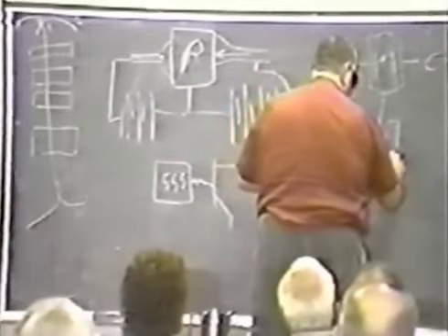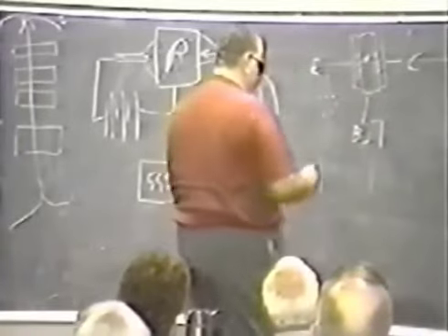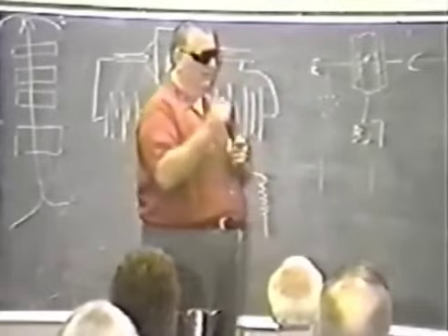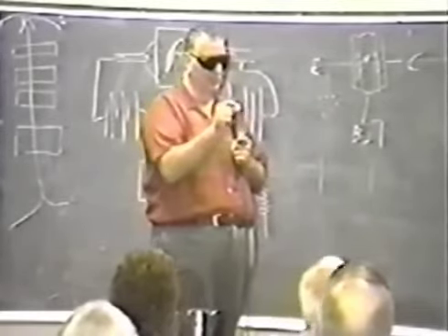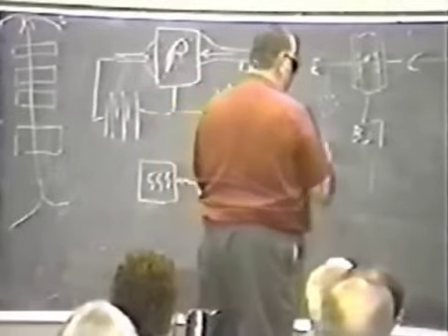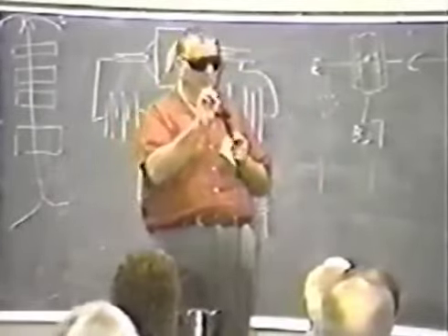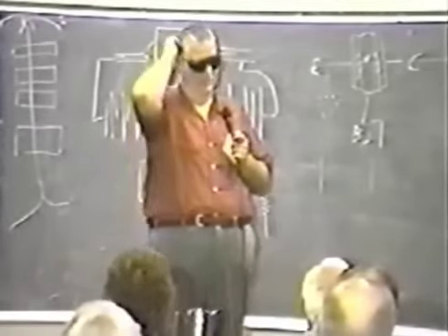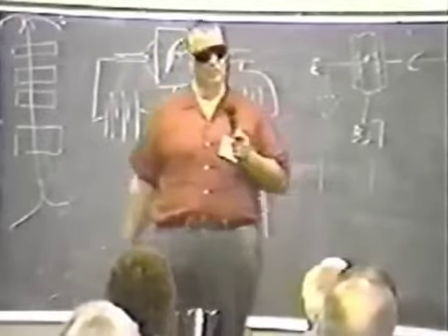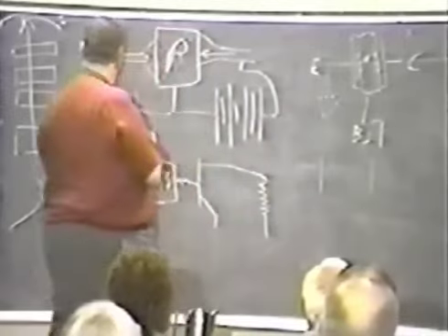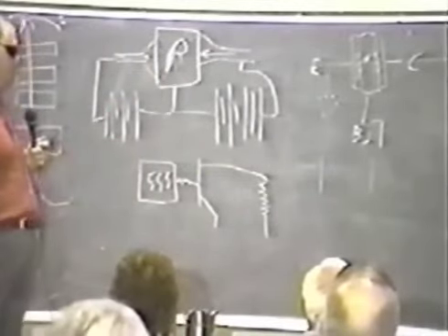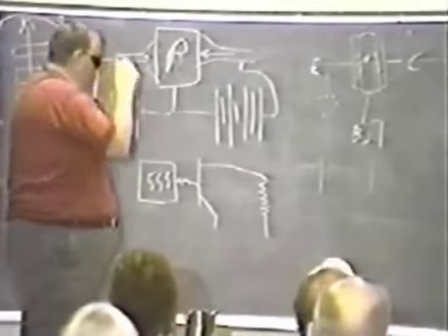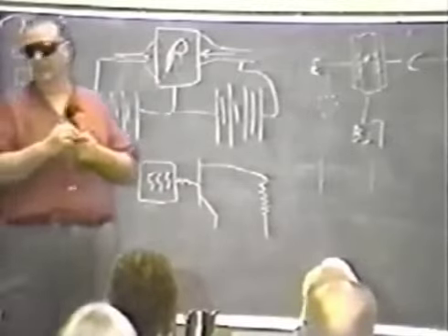You take your coil form. You rotate it. You take your feed, and it goes up and down each time it rotates. What you get is you build up a winding a little at a time, and you do 4 of these. Each one is called a pi winding. It's called pi because it goes from 0 to 360 degrees each time the form rotates once. And you just keep taking about number 60 wire, and you build it up. The whole impedance of this thing is about 1,000 ohms. The current through the transistor is maybe about 10 milliamps. The whole thing draws about 15 milliamps from a 9-volt transistor radio battery.